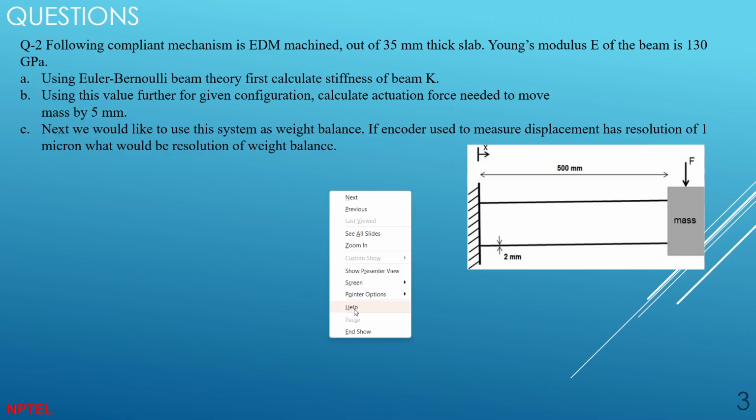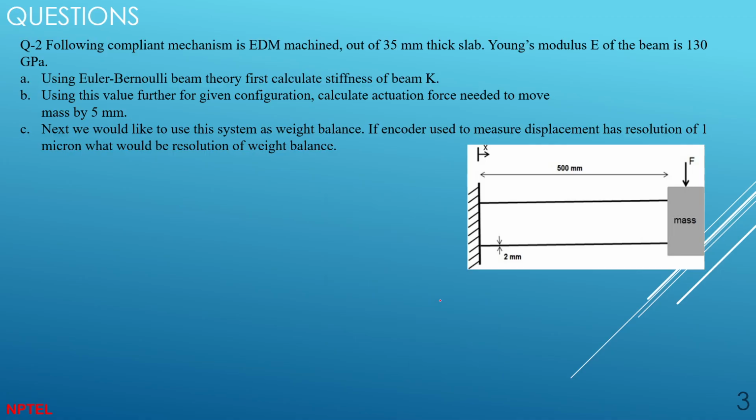Okay, so please don't solve this question like you solved it in, I think, the second year of mechanical engineering. In that case, the boundary conditions are different. That is a point weight cantilever, a single point weight. Yeah, it's an end point weight cantilever beam question. These are different. So please do remember it's a compliant mechanism. Okay? So the boundary condition will be different here.